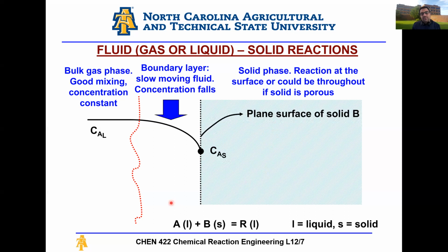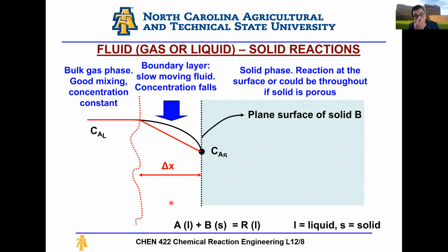Okay, and this is how it goes. You have a bunch of resistances. And when you think about mass transfer resistances, your mass transfer resistance, typical to any transport resistance, is a function of your driving force, which is your concentration, divided by your length scale, which is the distance, right? So in mass transfer, you typically see partial n by partial x, partial c by partial x.